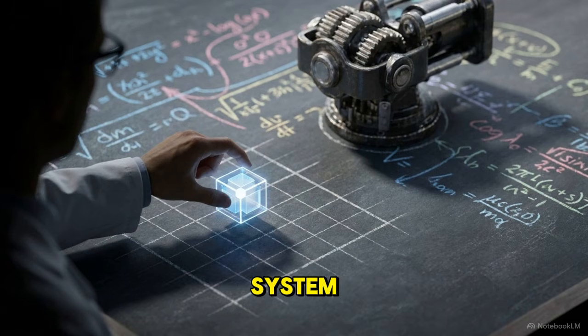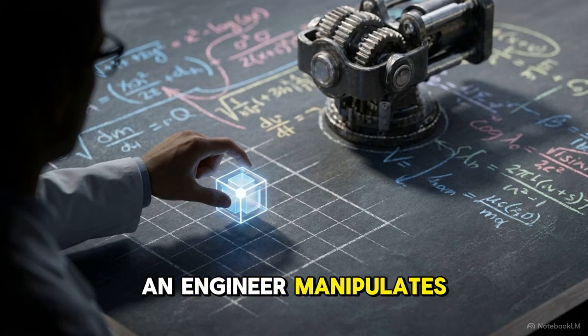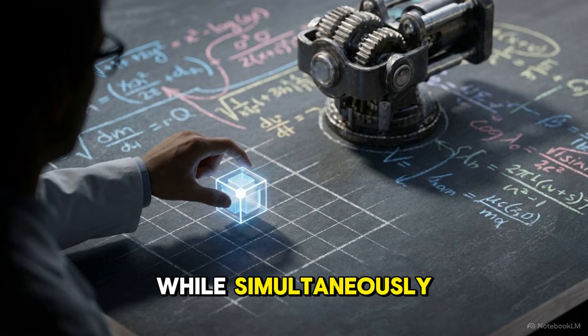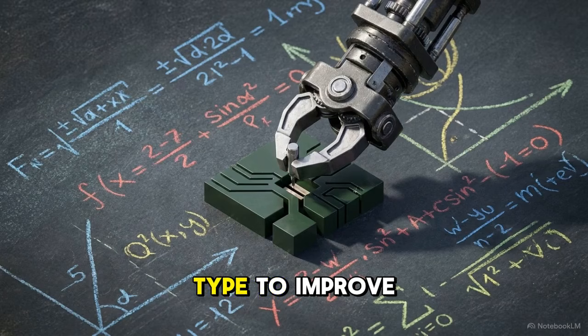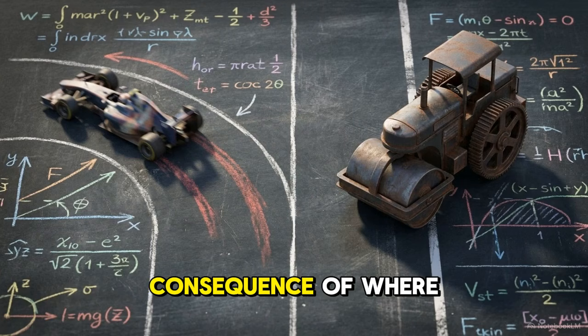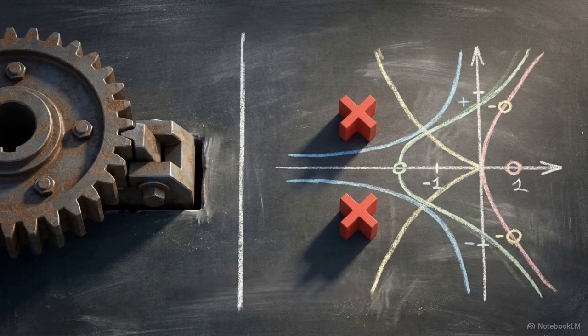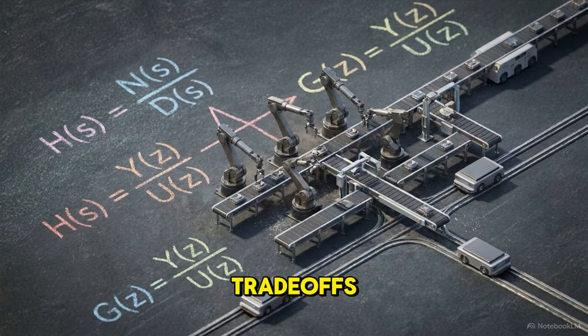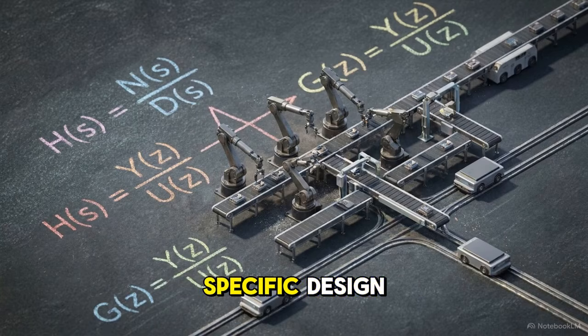Building an automated system requires deciding where to compromise. An engineer manipulates root locations to tighten the transient speed, while simultaneously altering the system type to improve absolute accuracy in the steady state. Ultimately, the balance between a system that is fast but prone to error, or precise but slow to react, is a direct consequence of where its roots reside. Control theory provides the mathematical framework to navigate these trade-offs and drive the system towards its specific design objectives.